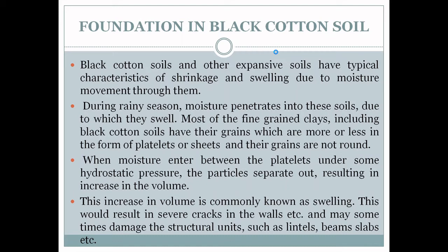Thus, the black cotton soil is highly sensitive to water. Due to the presence of fine clay particles, the black cotton soil will swell when it comes in contact with water, and the differential settlement of the building caused by the movement of ground due to the alternate swelling and shrinkage results in formation of cracks.